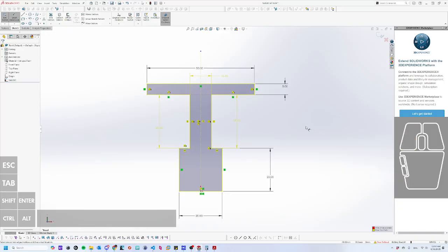I see that a bunch of it is yellow, and I'll just systematically work my way inside out, trying to get rid of whatever I think might be over defining it. In this case, I can tell already that this one over here is the thing I want to delete, but possibly, maybe if I make them not symmetric, let's hit escape.